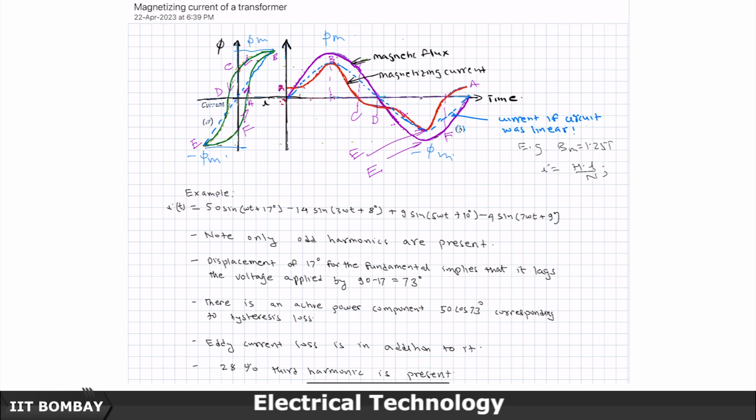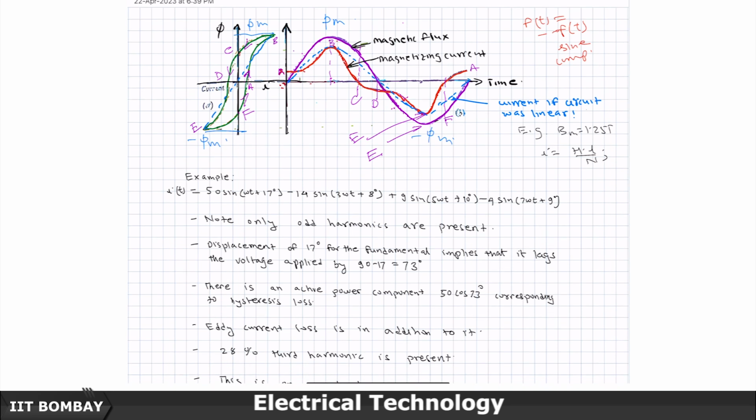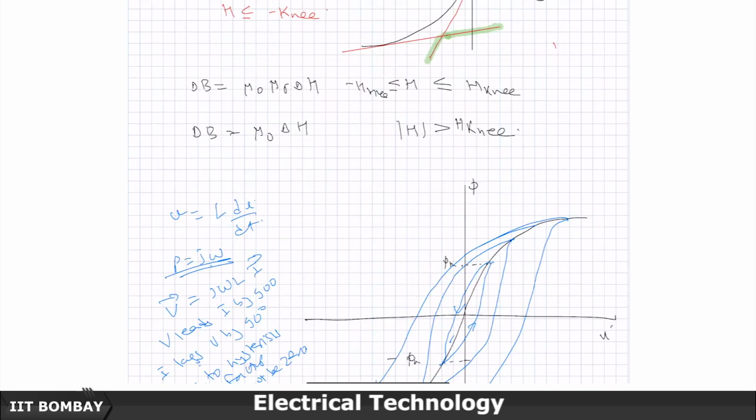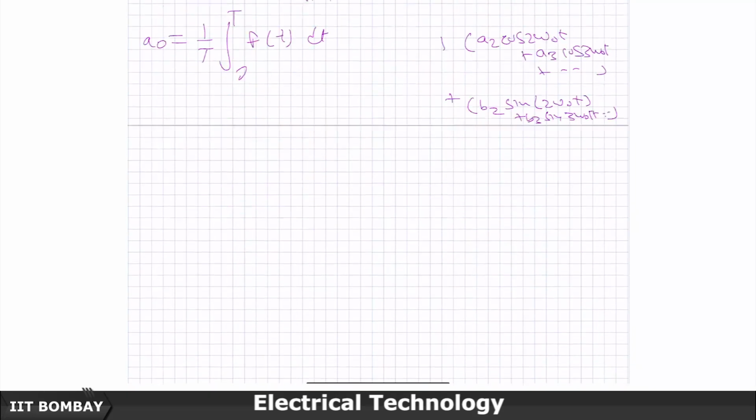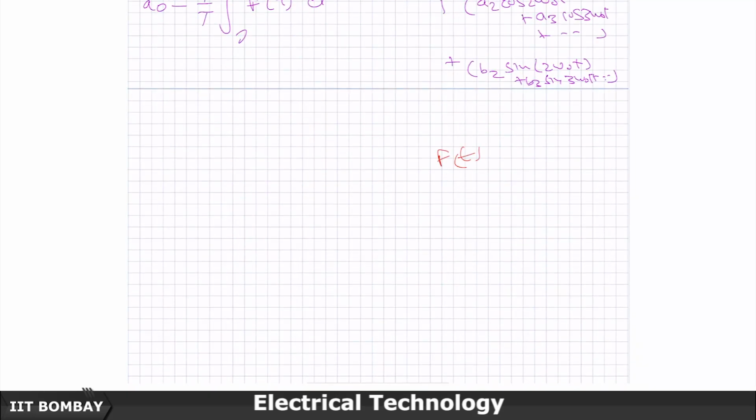and the waveform is going to look like all sines because of the odd symmetry. The odd symmetry means f of t equal to minus f of minus t. If a waveform is like that, in its Fourier series, if you go into a bit more detail, you will see that it has only sine components, and if it has what is known as even symmetry, the even symmetry means f of t is equal to f of minus t, a waveform like this.